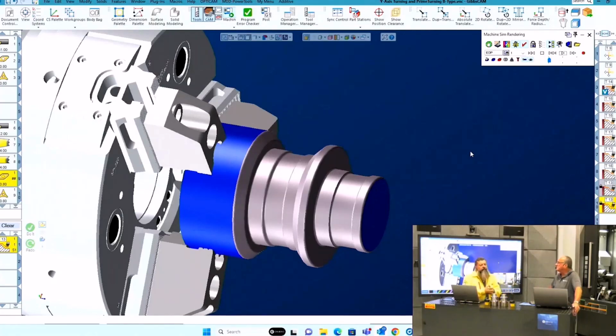When you have your intermediate tools designed for these blocks, when you have those properly designed, you're going to create code for y-axis prime exactly the same way you create it for x-axis prime. Exactly. Or traditional prime. The software is smart enough to know how and where to flip that tool. So for those of us on the programming end and those of us who are trying to push applications through, you don't have to learn two different sorts of things.